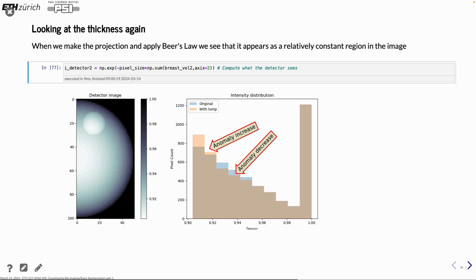And that transmission could be either that you have a thick thing or that you have a combination of two materials that gives you this different thickness. And that is the ambiguity that you can't tell. Is it caused by a material mixture or by more material? And that you can't tell from the radiograph. For that you need to do a tomography to tell the difference if there is a region of something else.